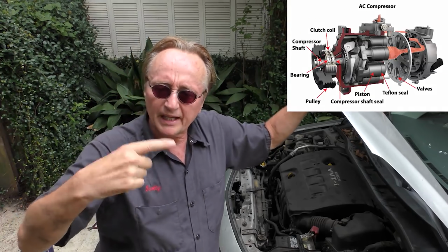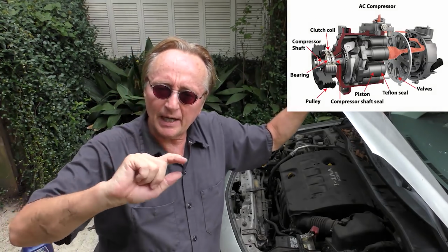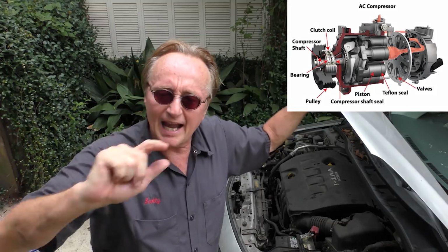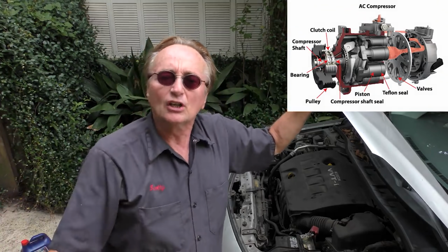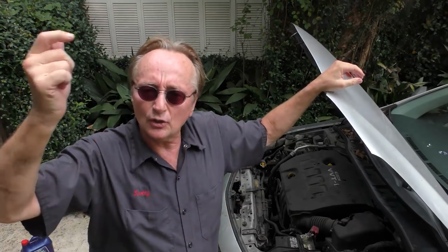But that seal has to allow a little bit of refrigerant and refrigerant oil to leak out to lubricate that seal. Because if it ran perfectly sealed, it would run dry on the outside, the shaft would spin, burn out the seal, and it would all leak out. So all cars leak refrigerant over time. This particular one's never had any added. It's 10 years old, so it's a good thing to fill it up with a factory load.